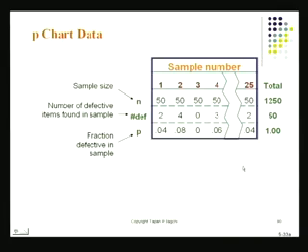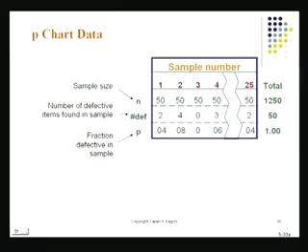When this is done, every time, like in the X bar chart or the R chart, the moment the chart goes beyond the control limit, stop the process, take a look at it, and see if indeed everything is okay, or yes, something did go beyond the set limit, and then you'd restore the process to its normal state of affairs.